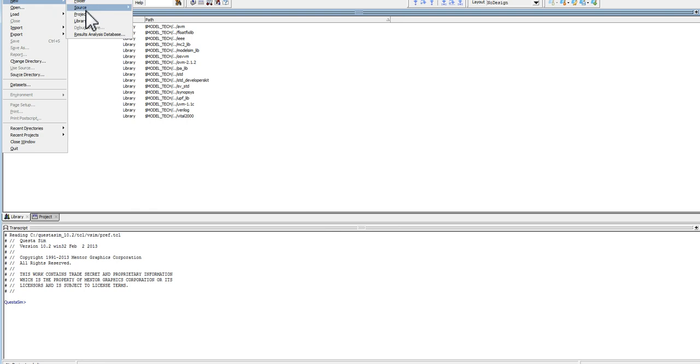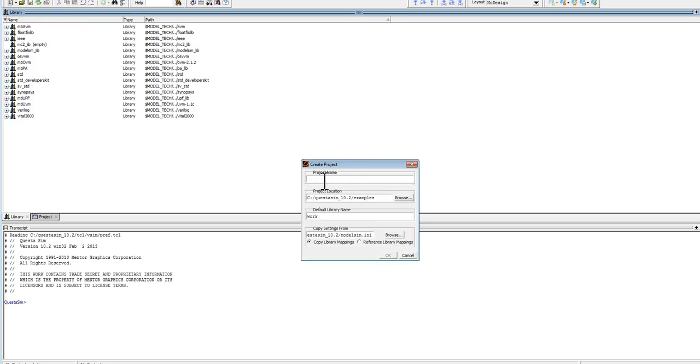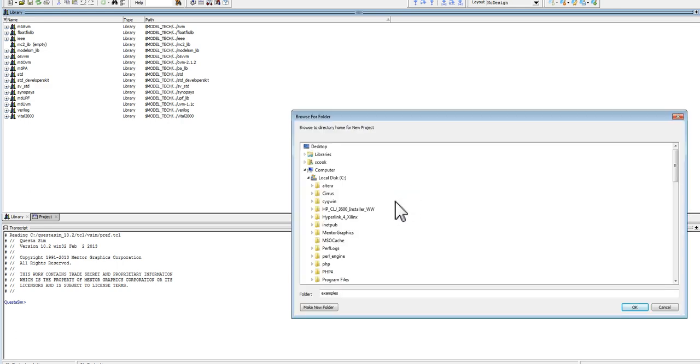But less than 10 minutes of loading in a DUT, mostly with mouse clicks, loading in BFMs, having connections made automatically, having a system Verilog bench made with the scripts and a directory structure was fairly painless.